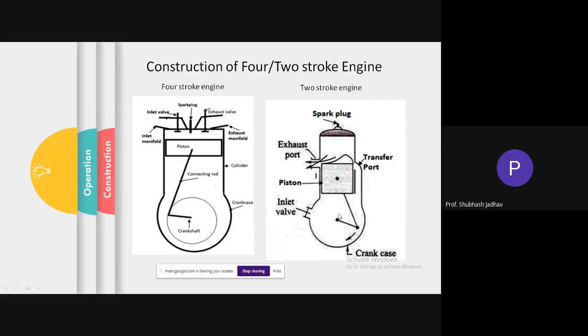Whenever this piston moves up, what happens here? A negative pressure is created, and this negative pressure will result in the opening of this reed valve. So this is a reed. Basically, it is something like a small flat plate covering a hole. It is called a reed. Suppose the reed valve is attached over here. Now what happens? The hole is like this, and on the right side of this wall, there is that flat plate covering the hole.